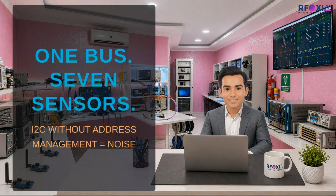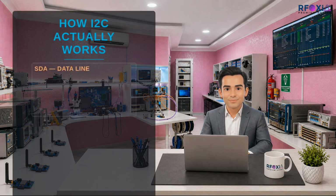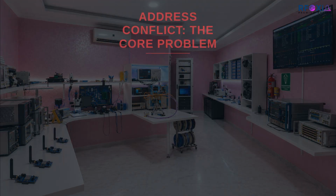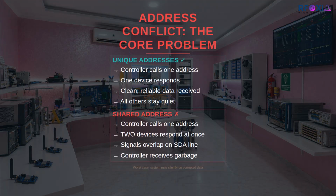I2C is a two-wire serial communication protocol. It was designed by Philips in 1982 and it has aged remarkably well because the idea is genuinely elegant. You have two lines, SDA which carries data and SCL which carries the clock. Every device on the bus is either a controller or a target. The controller initiates transactions. The targets respond when called.